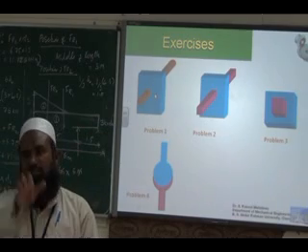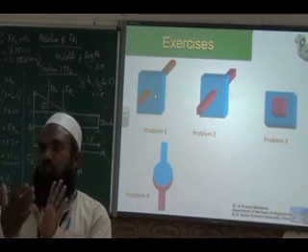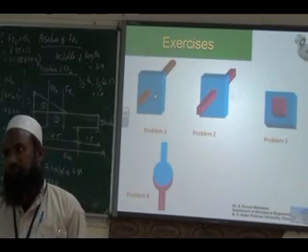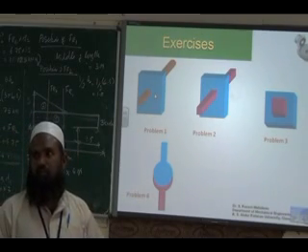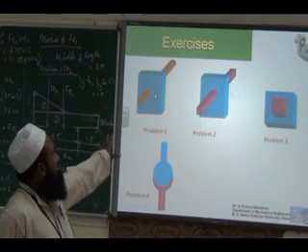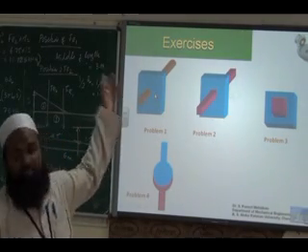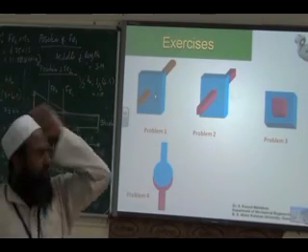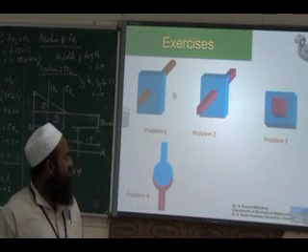Okay, it can rotate and translate. There is no collar, no restriction for translation, so it can freely move in X direction. So translation in X, Y and Z will be there. Reactive forces in Y and Z will be there, and two moments will be there.